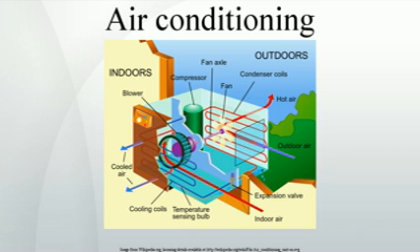Evaporative air coolers, sometimes called swamp coolers, do not have a compressor or condenser. Liquid water is evaporated on the cooling fins, releasing the vapor into the cooled area. Evaporating water absorbs a significant amount of heat, the latent heat of vaporization, cooling the air. Humans and animals use the same mechanism to cool themselves by sweating. They have the advantage of needing no hoses to vent heat outside the cooled area, making them truly portable. And they are very cheap to install and use less energy than refrigerative air conditioners.